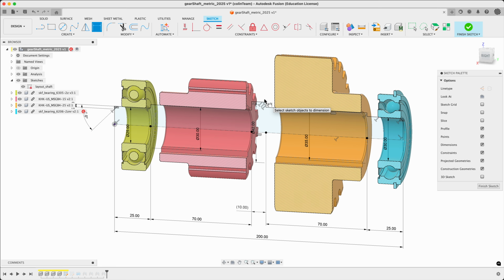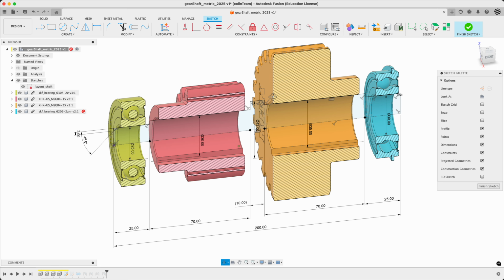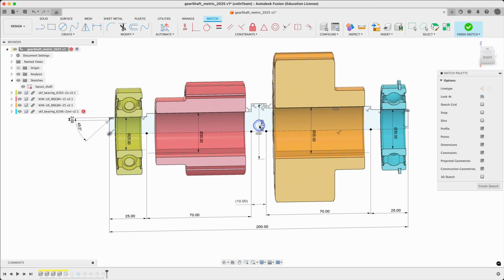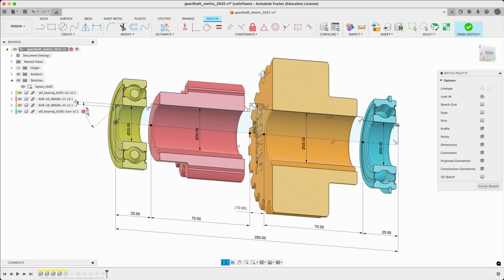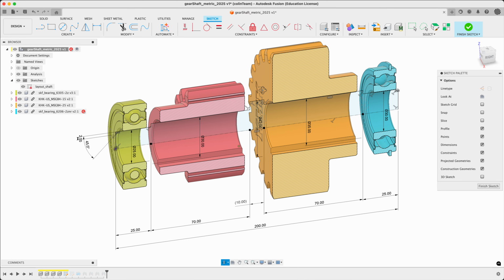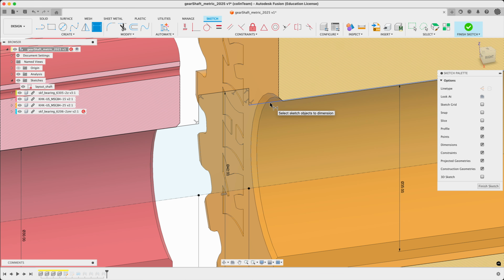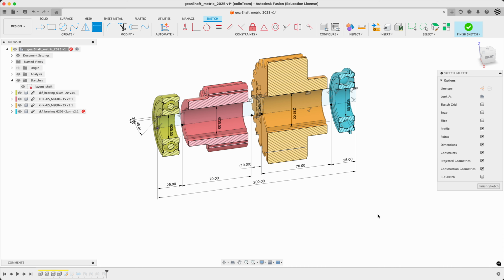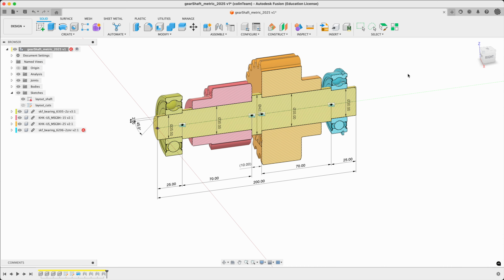The advantage of using a lower shoulder is we start with a smaller blank, which saves a lot of material, machining-wise. So this is good. You want to keep the shoulder as low as we can, and since we do have really tight chamfers on these gears, that seems to be good for us. So let's stick with that for now.